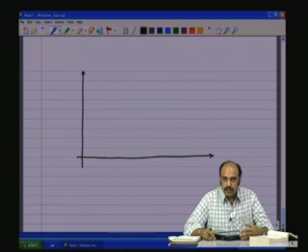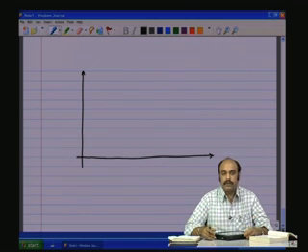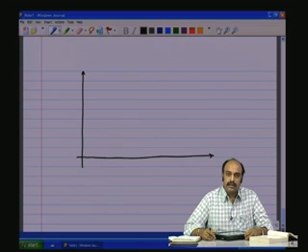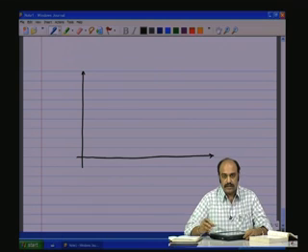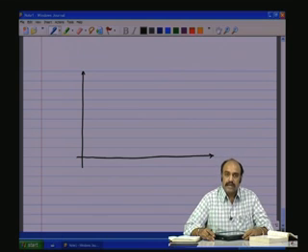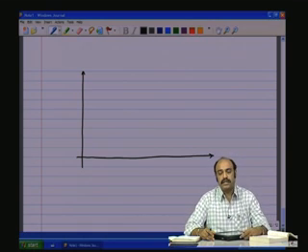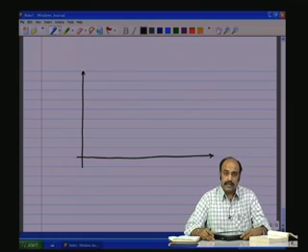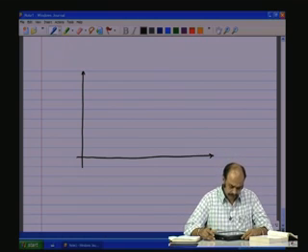Then you have the over compound to take care of the loading effect on the field, plus also the loading effect of the armature winding resistance on the output terminal voltage. And of course, the differential compound, so that you want to bring down the output voltage drastically to limit the short circuit current in some applications like DC arc welding.